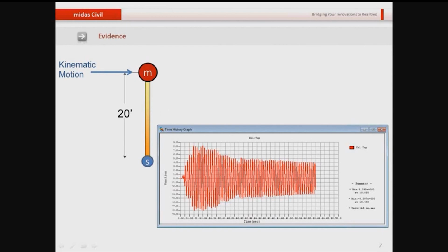With the support we have applied stiffness, mass, and damping matrix, and as a result, I have plotted the displacement of the top of the pier against time, and you can see the damping effect coming into the picture as time proceeds. So in this manner you can verify very easily whether and how the support and the springs with the different types of matrices are behaving.